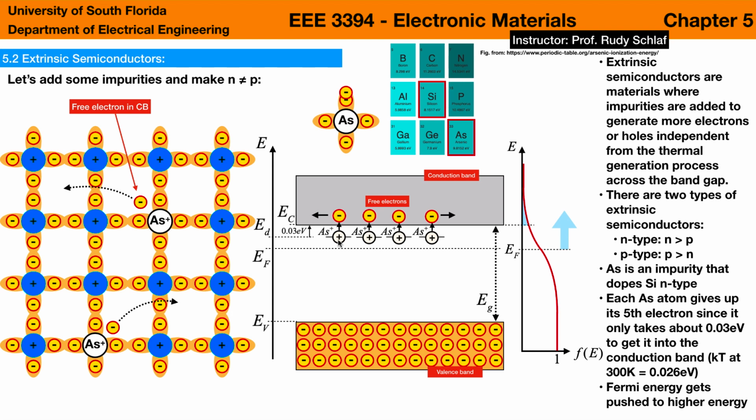That means, one for one, each of these arsenic atoms that one can implant into the silicon wafer will give their electron into the conduction band. And so this is a phenomenal way to control the conductivity of a semiconductor material by simply putting a certain amount of arsenic in a well-controlled manner into the silicon wafer. And with that we can adjust the conductivity.